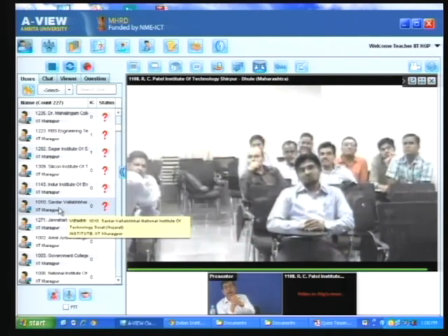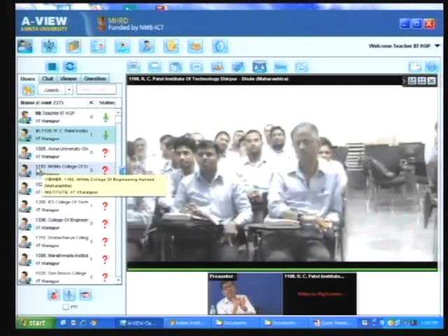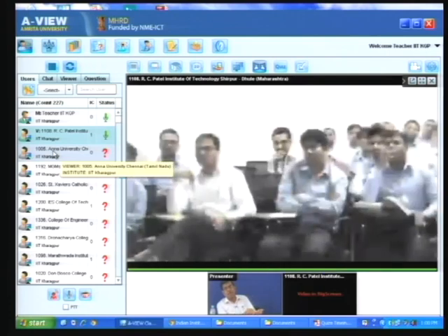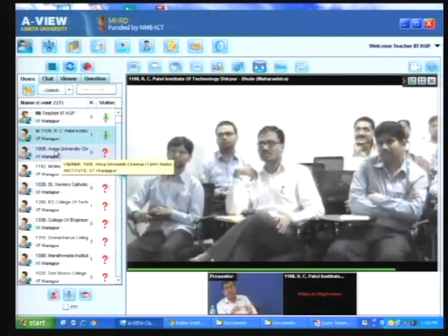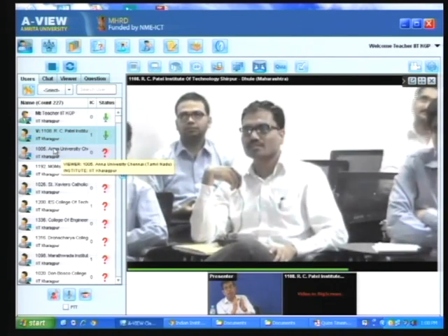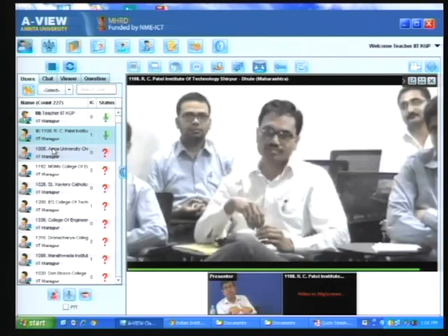And boundary conditions, initial conditions are irrelevant here. We are not going for any theoretical analysis based on conservation equations like Navier-Stokes equation, Bernoulli's equation, Euler's equation. These principles tell you what should be the number of non-dimensional terms defining a problem, which is reduced. Try to understand the beauty of the problem. If a problem is defined by m number of physical variables, this can be reduced by n number of physical variables.